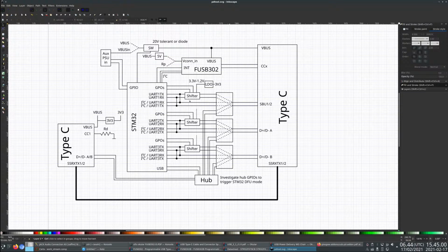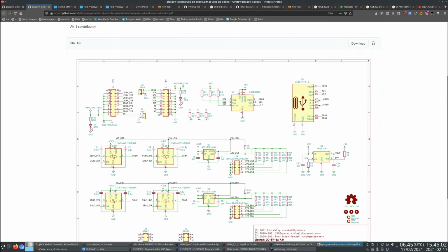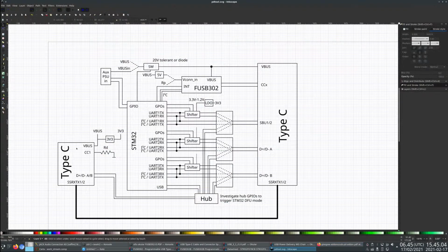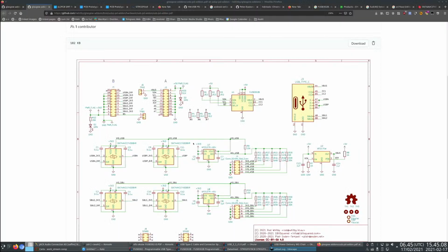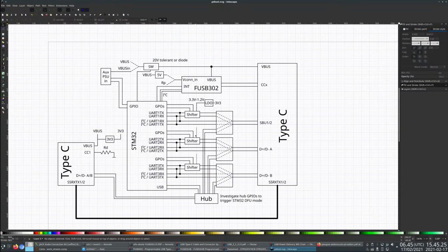So the questions here are, well, I'm just going to use these shifters unless there's a good reason to change them. Yeah, no problem. I'll review it to make sure that it makes sense, but it's always good to start off with something someone else made and already thought about. So yeah, the same regular design. And by the way, it's only going to be a single LDO for everything here because we're switching between 3.3 volts and one fixed other voltage.